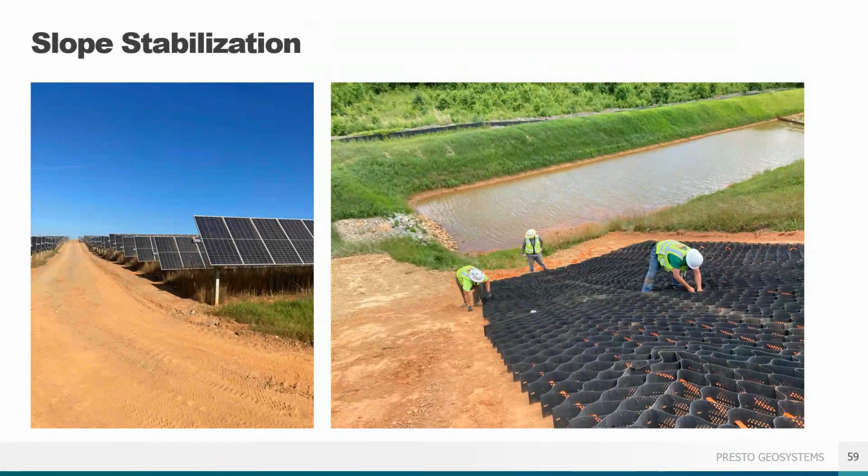This is a vegetated slope project at a solar farm and allows us to show some great step-by-step install pics while pointing out those best practices with ATRA tendon clips. The solar site included a sloped area leading to a large detention pond for stormwater management, and GEOWEB helped stabilize that slope and control erosion.